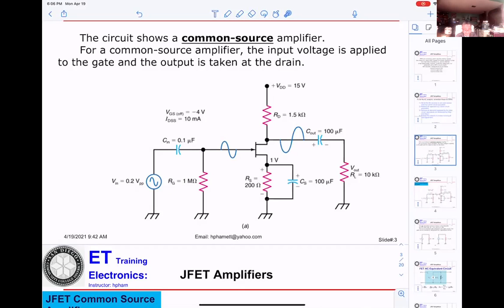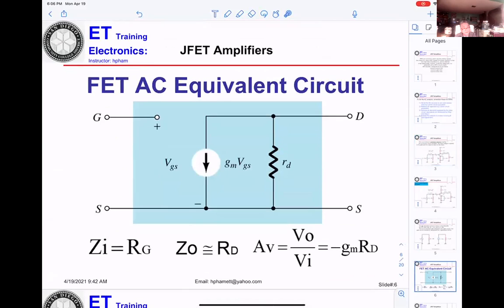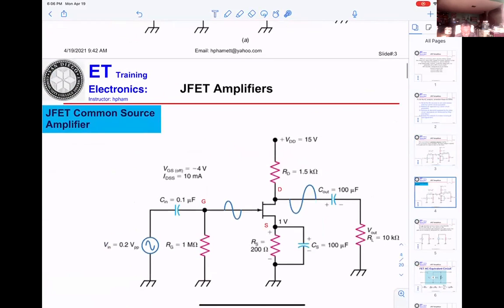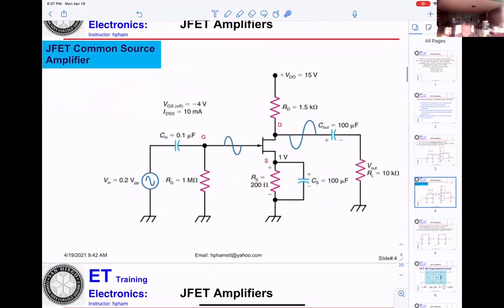I don't think it has anything to do with the cutoff frequency. If you want, you can run a simulation for this circuit and try changing RG to a different value, then you can see whether the frequency is affected or not. But to me, RG equal to 1 megaohm is just an input impedance for the amplifier.